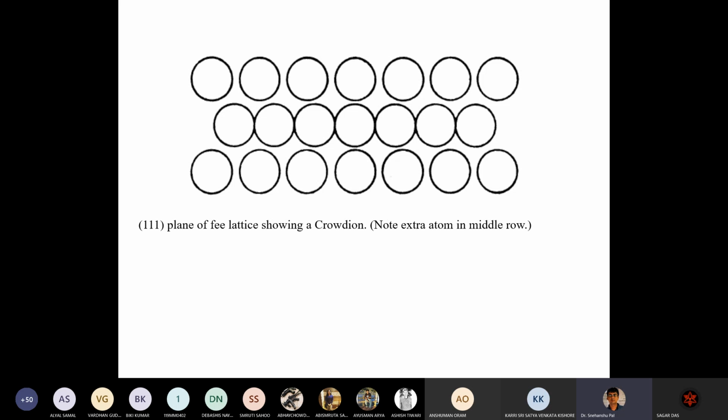You have to take into account that an interstitial atom means only that there is one more atom than there are sites in a given small region. Similarly, for a vacancy, the site is vacant, but the region contains one fewer atom than the sites. So now we have to use the overall region concept to understand such defects, because the underlying mechanism of diffusion compels us to think like that.